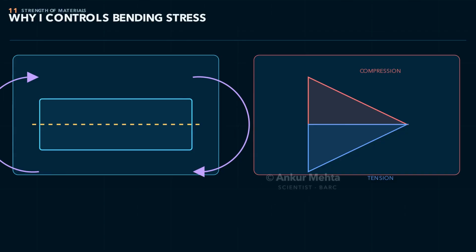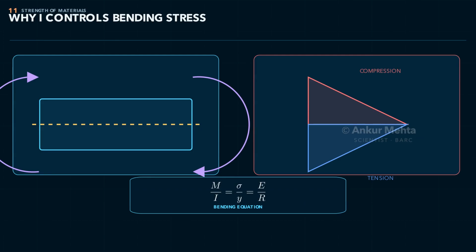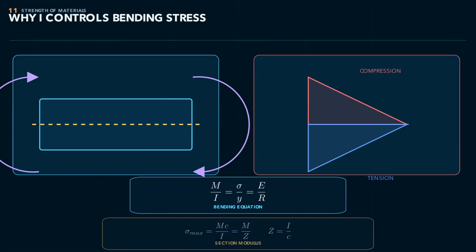For the same bending moment and material, a larger I reduces stress, but strength depends on I divided by the extreme distance c, not I alone. Moving area away from the neutral axis generally increases both I and section modulus, which explains the efficiency of I sections, box sections, and D beams. The sign of stress changes across the neutral axis, where bending stress is zero.